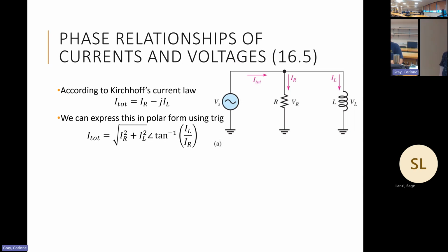So in the case of series, we're looking at the change in voltage as we go across our components. While we're in parallel, we look at the different currents inside of them because, again, they should have the same voltage across them. Kirchhoff's voltage law still applies, but it's the current that's going to be different between those paths.